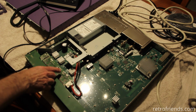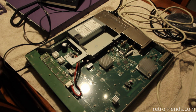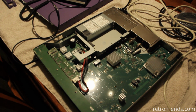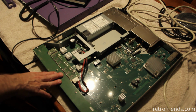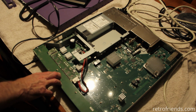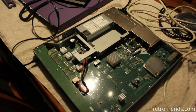The alternative, I can also remove this chip again, and then I can test the pads and see if I have any goofy voltage on them that shouldn't be there. There's not a whole lot of things that will make a chip like that heat up. Having replaced that chip, I've discovered that maybe it wasn't a solder ball, maybe something else, and that would sort of better explain how the diode was also faulty. I'm going to take that board back out and check passives, resistors and capacitors, and see if I can find a shorted or an open device.